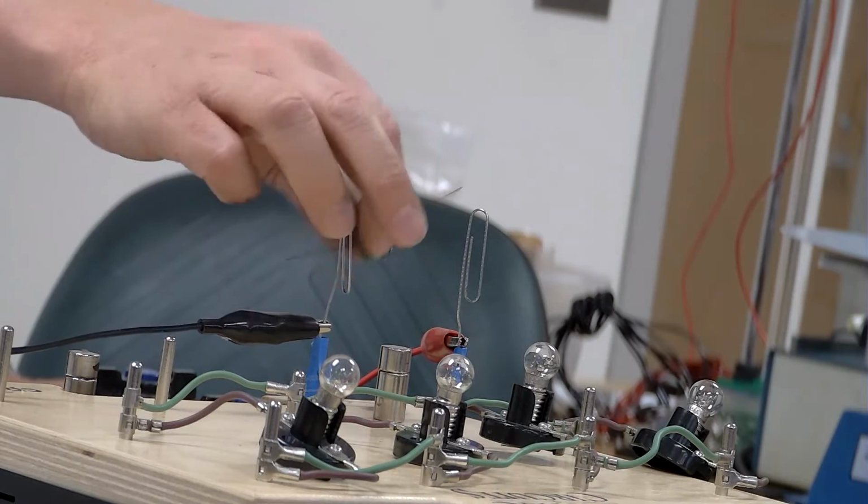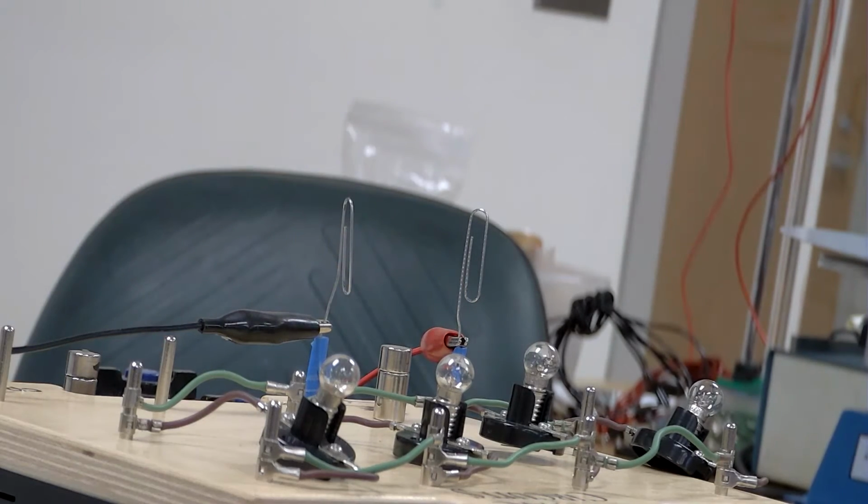So what I had to do, this wire has a coating on it. And so I had to scrape off that coating in order for current to go through the loop of wire into the other paper clip, right? I should have taken one and stripped off all of that coating. Because if all that coating gets stripped off, then as it rotates, it's going to feel that force that's going to want to make it rotate back to where it started.